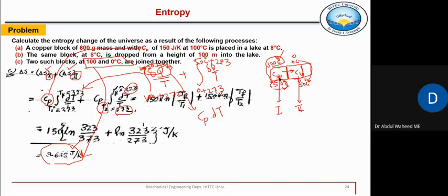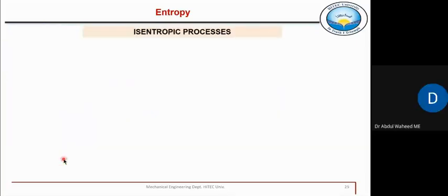सही है सर। ठीक है, वो जो सराउंडिंग का मतलब सिर्फ एटमॉस्फेयर नहीं होता, वो depend करता है application to application। सराउंडिंग का मतलब कुछ और भी हो सकता है। इस केस में हमने atmosphere के effects को include नहीं किया। अगर वो भी include करें तो entropy change will be, because सारी की सारी हीट कॉपर 2 को नहीं जाएगी, कुछ हीट यहाँ पे भी transfer होगी into the surroundings. Then you have to add delta S of copper 1 plus delta S of copper 2 plus delta S of surroundings, जो ambient जिसे आप कह रहे हैं, that will even be a bigger number. जी ठीक है, वो हमने नहीं include किया। ओके ठीक है.